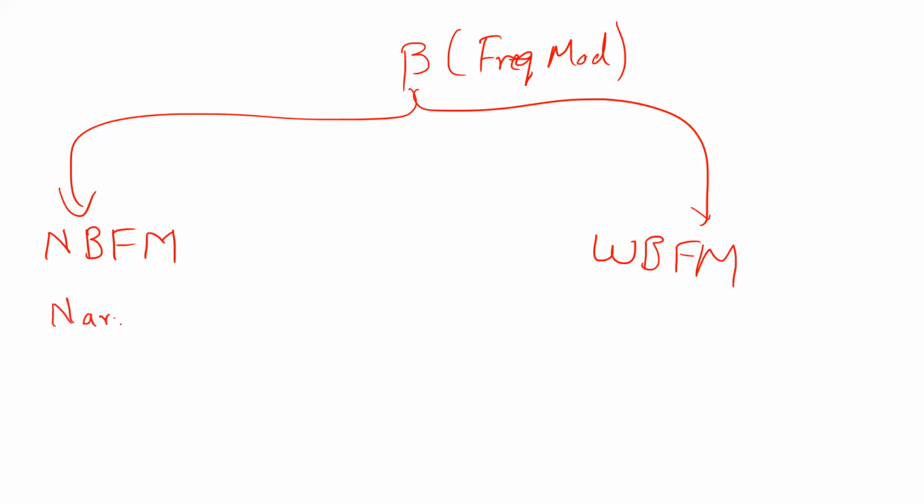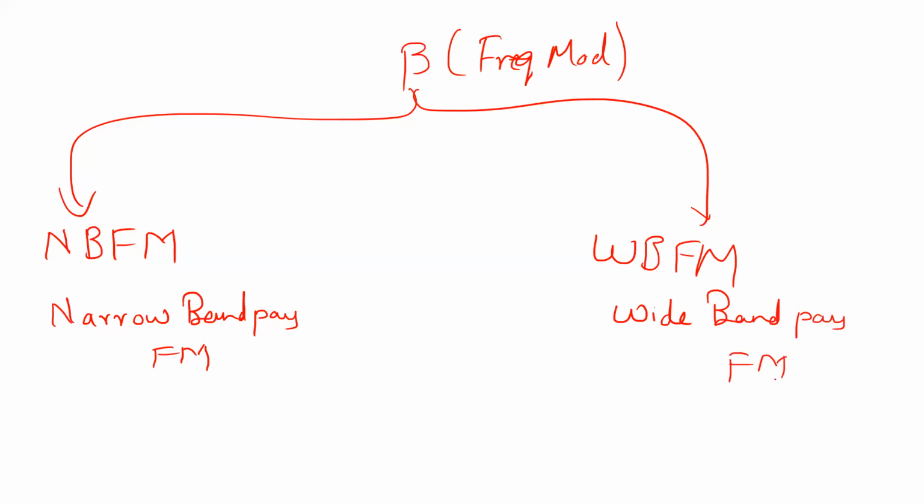This is the narrow band FM. Right, so wide band, they have different band passes, the low band pass and the high band pass, all those things. Here, narrowband, the beta value is smaller than 1. Here, the beta value is greater than or equal to 1. Clear? Any doubts here, Jerry? Wait, let me digest a little bit. Modulation. Okay.